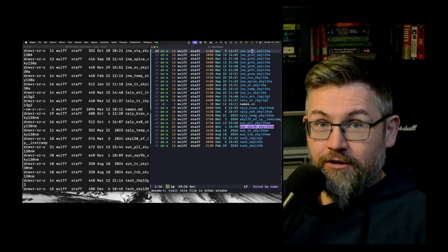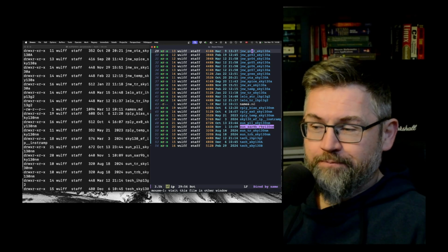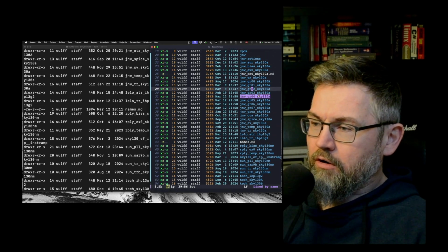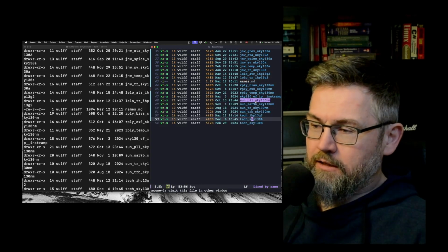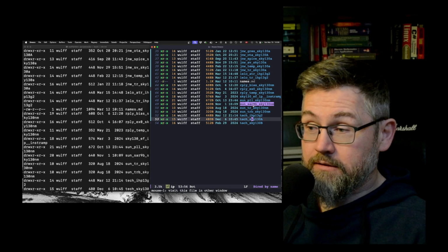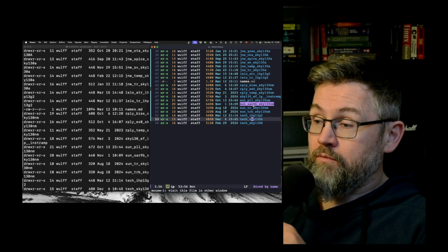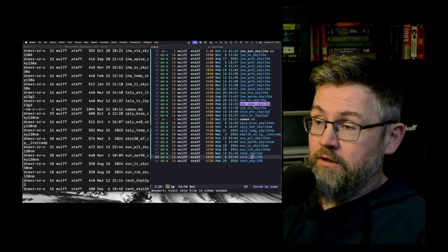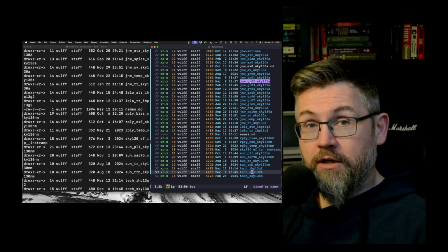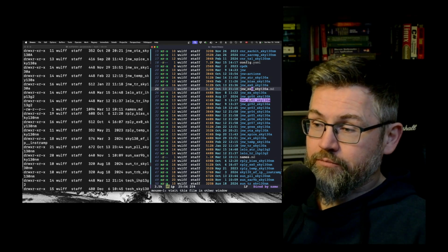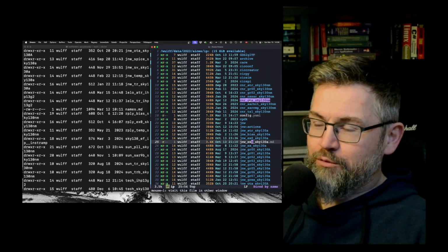Now, Sky130 is not really a technology that's easy to use anymore, so I need to port it to IHP. And all these different libraries are different designs that I've been playing with. I think there's a PLL here, there's an ADC, this is the ADC I taped out on Tiny Tapeout 6. And there's a bunch of designs, all the GR stuff, that's from groups in my course, Advanced Integrated Circuits, where I forced the students to make a temperature sensor. But then there's also some tools in here.